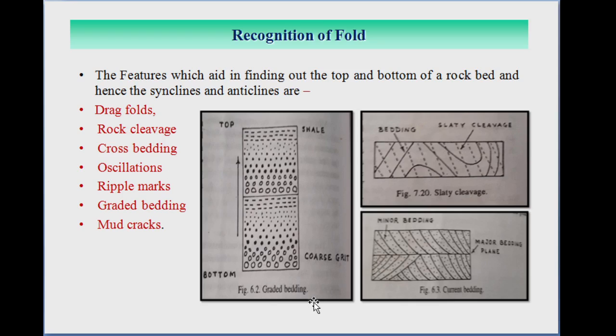In the graded bedding, or you can say the sedimentary bed, the coarser grains are always at the bottom. In the graded bedding, coarser grains are always at the bottom. Okay, so with this trick we can identify the fold.